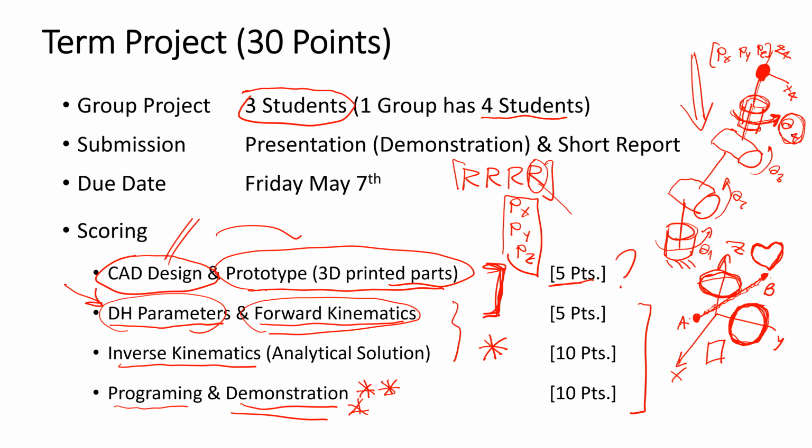The rotation of joint 4 can only change the orientation of the axis at the end effector. But in our assignment, we only care about the end effector position. So maybe put the robot in this way, you cannot get the benefit of the joint 4 to obtain the position.